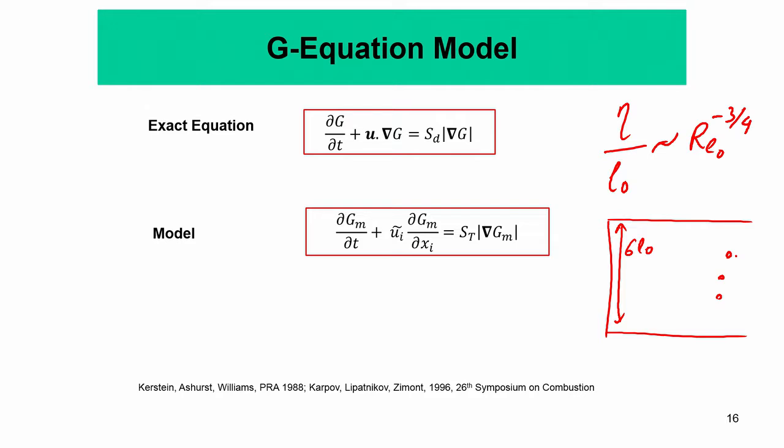Similarly, that is why we went to the RANS model, where you do not need such fine grids, because you are only interested in the evolution of the average quantities. Whereas in the LES, as I said, you are only interested in the evolution of the filtered quantities. Now, those are not the instantaneous quantities. So, you lose some knowledge of what happens instantaneously, but we are more interested in the averaged statistical behavior of an engine rather than what exactly happens at different instants.